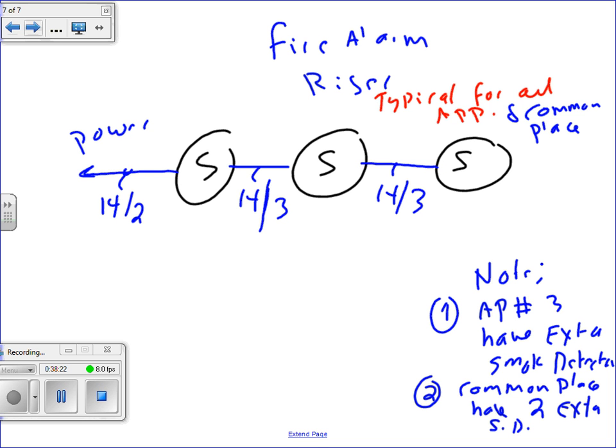It tells you, for example, if you have a full fire alarm system, low voltage, you cannot install the fire alarm cables in the same conduit with power, lighting, and equipment circuits. Common sense. So these are the large things that they talk about: the installation for low voltage fire alarm cable. That would be Article 760, if I remember that right. Yep, 760 is the fire alarm system.